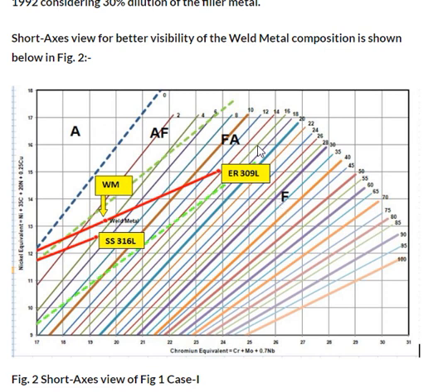So austenitic stainless steel most of the time solidifies in modes A, AF, and FA. Preferably it should solidify under FA mode to prevent hot cracking issues. And this duplex ferritic austenitic weld metal solidifies in a fully ferritic structure.